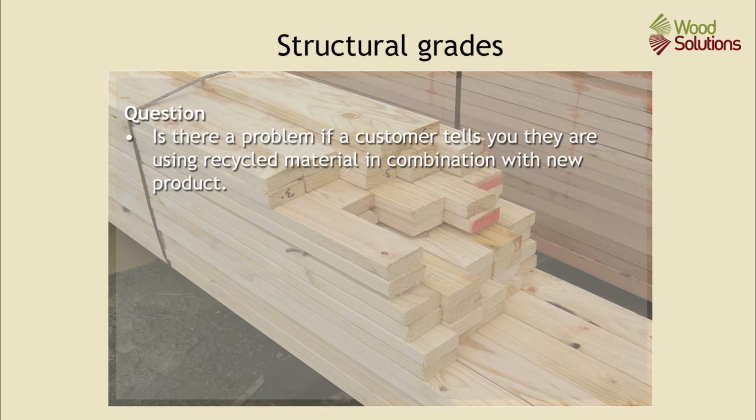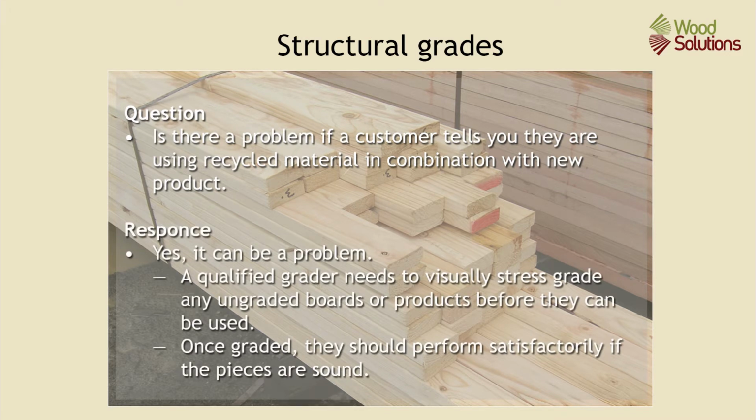Is there a problem if a customer tells you that they are using recycled material in combination with new products? Yes, it can be a problem if the recycled material doesn't have a stress grade marked on it. A qualified grader needs to visually stress grade any ungraded boards or products before they can be used. If they are not graded, the building surveyor may insist that they are removed. Once they have been graded, there shouldn't be a problem if the pieces are sound.